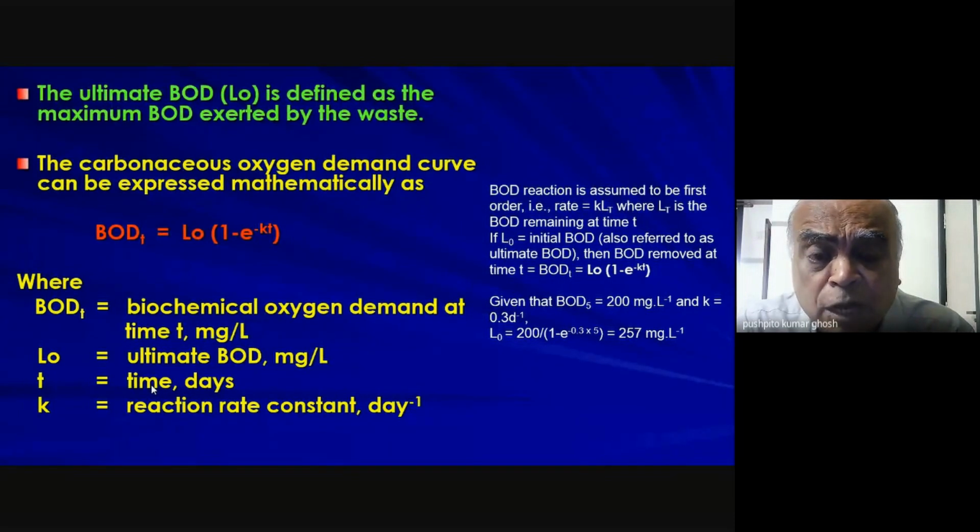But you also need to know the ultimate BOD, which is where all of the organics got completely chewed up and formed carbon dioxide, and that is known as L0, the ultimate BOD. So obviously, to reach the ultimate BOD value, you may require more than 5 days.